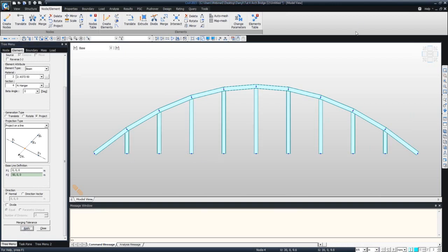There we go. Okay, so the thing is, what you need to do is you need to select these nodes first before you put in that baseline. So that's my mistake. So just make sure, when you're doing this on your own, that you select the nodes that you want to extrude prior to selecting your baseline. So that was a mistake on my part, so my bad there.